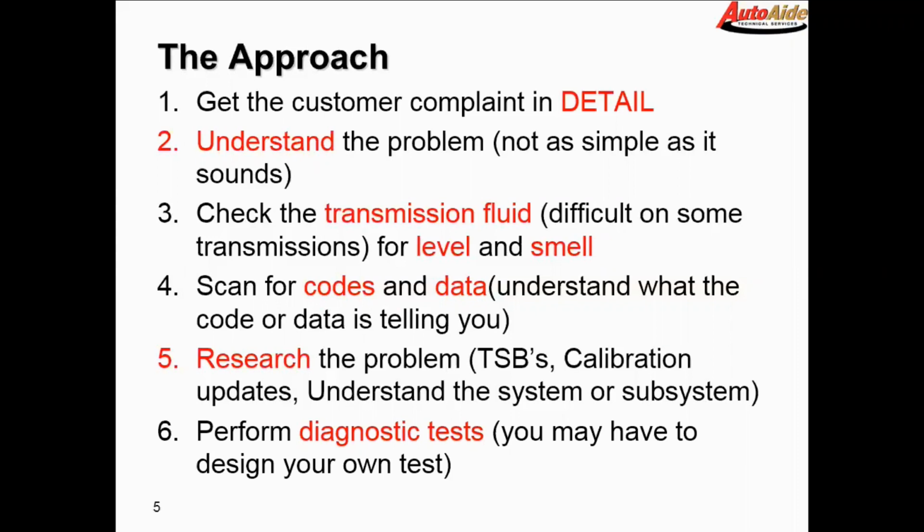A lot of times, especially with transmissions, at the dealership level they have a lot of specialty tools, special testers that plug into the bulkhead connector, and they can literally drive the transmission with some of these test boxes, check solenoids and that sort of thing, and we just don't have access to that stuff. So you may run into a situation where you have to do a workaround or get creative, or whatever the case may be.